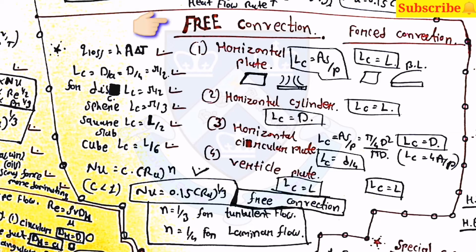Here for the free convection for horizontal plate, LC is equal to AS by P. Similarly for the forced convection, LC is equal to L. Then in the horizontal cylinder, LC is equal to D and LC is equal to L. Then for horizontal circular plate, LC is equal to D by 4 in the free convection, and in the forced convection LC is equal to D. Then vertical plate, LC is equal to L for both the convections.